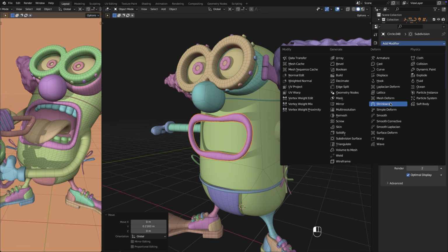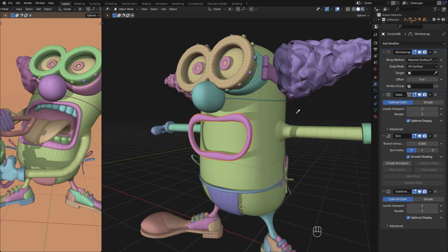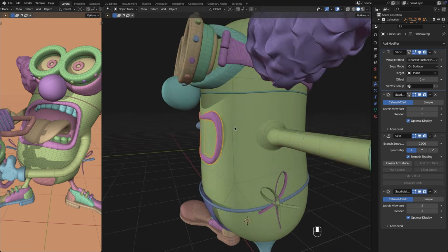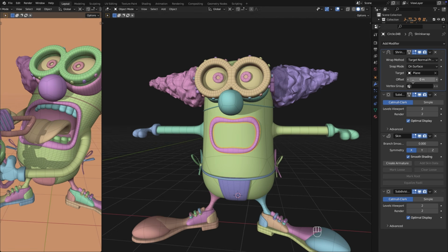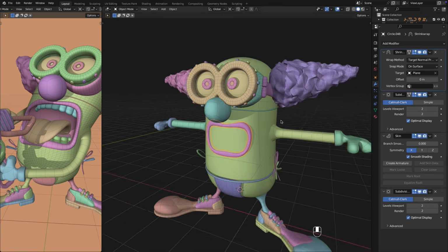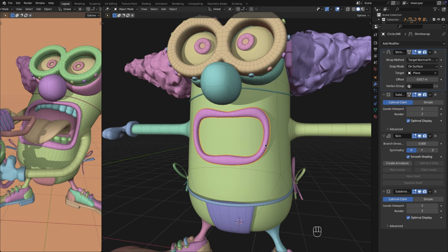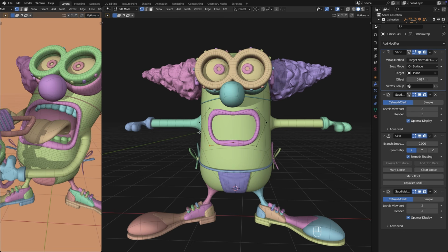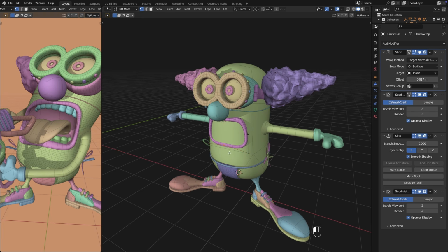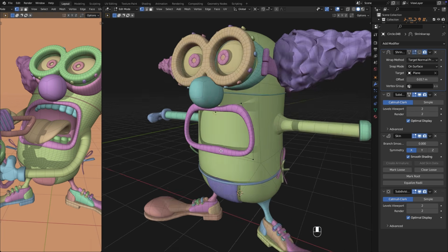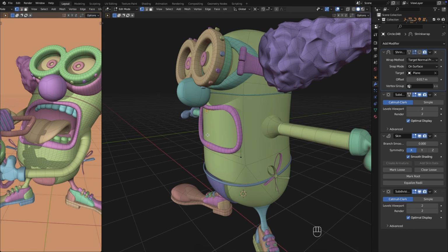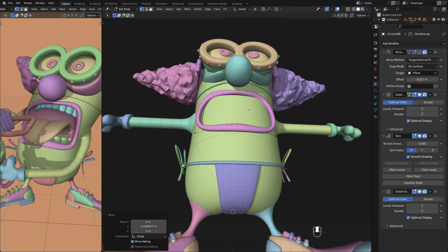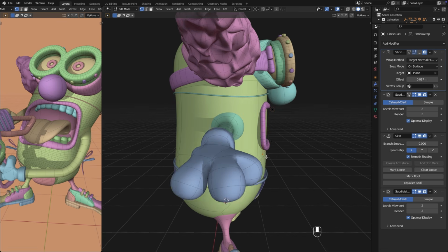Now if you look at my modifier stack, you might notice a disabled Shrinkwrap modifier sitting there. Honestly, I tried to use it to wrap the lips automatically around his capsule body, but it was acting way too unpredictable. Sometimes, just manually grabbing 6 vertices and moving them yourself is 10 times faster than fighting an algorithm. The lazy skin method wins again.